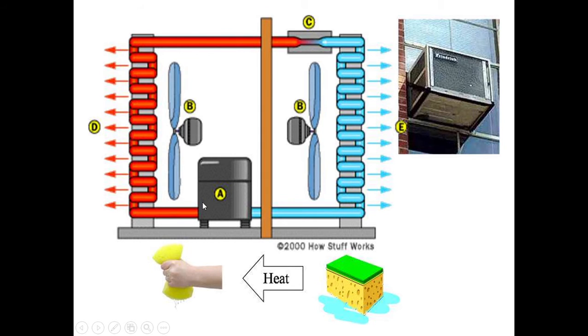So you have the compressor present at the bottom and the expansion device here. In this case you have two blowers here, that are used for increasing the airflow rate only. All other components are the same: evaporator, compressor, condenser and expansion device.